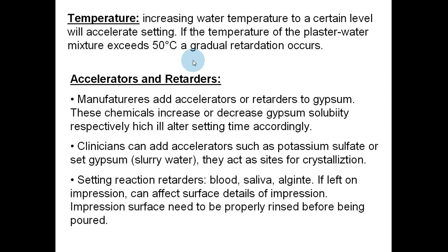Temperature. Increasing water temperature to a certain level will accelerate setting. If the temperature of the plaster water mixture exceeds 50 degrees Celsius, a gradual retardation occurs. Accelerators and retarders.